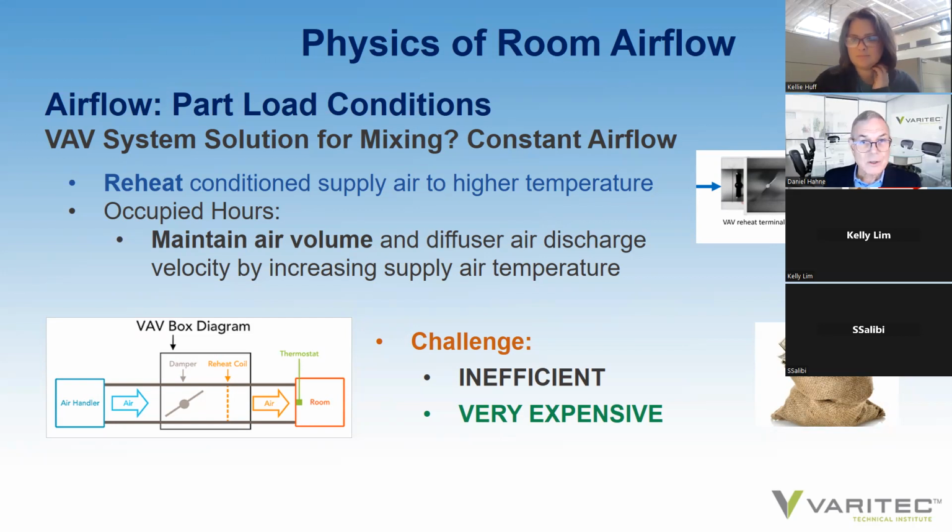So humidifier systems can be added to a system. Now for dehumidification, make sure that the dew point off the supply air coil is not only low enough to absorb the moisture gain in the building from occupants, running water, maybe fountains, etc., and outdoor air humidity, but it also has to have a low enough dew point to take in the humidity component in the side stream bypass as well.